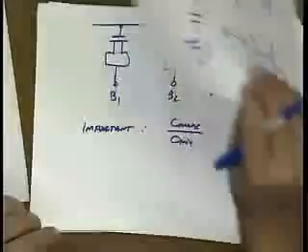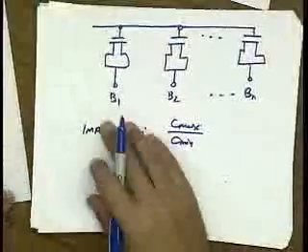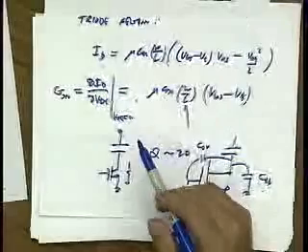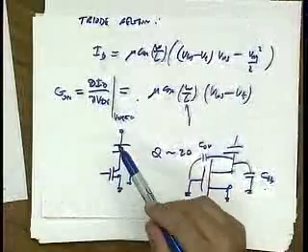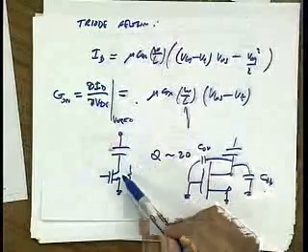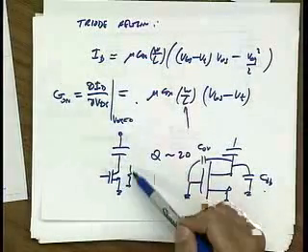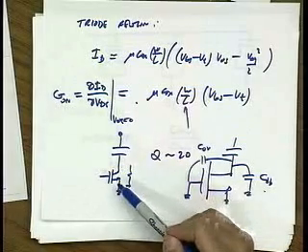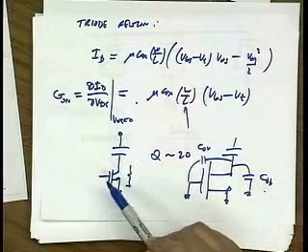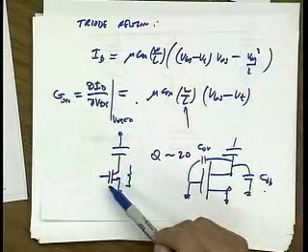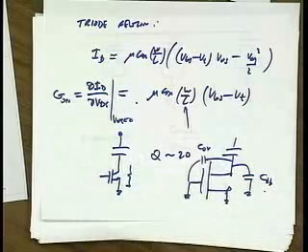The other neat thing, which there's no time to show you guys, but you can see pretty clearly, is that I can actually scale these devices so that they have constant Q. In other words, if I double the capacitance, then I can actually live with double the parasitic. So I double the size of the switch. That doubles its conductance, so the net Q remains the same. So if I just design a unit cell element and scale it, the overall Q is really determined by the quality factor of one unit cell. Okay?